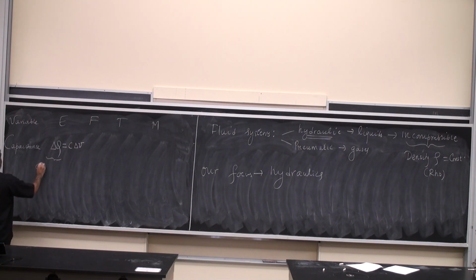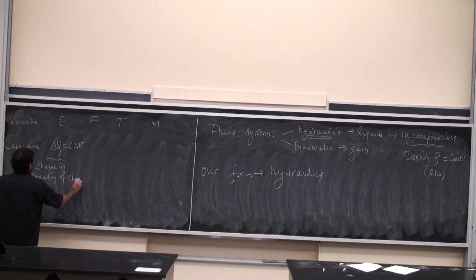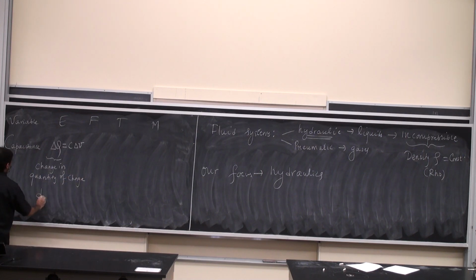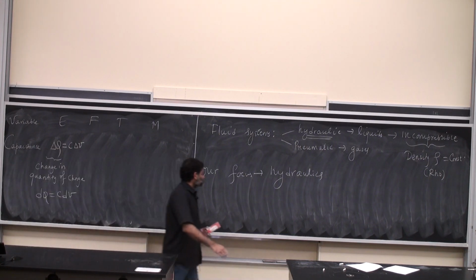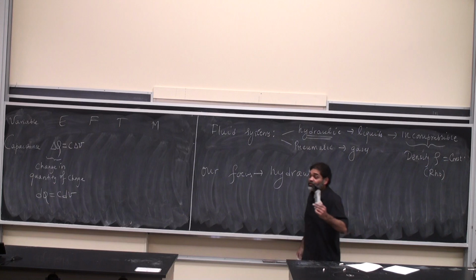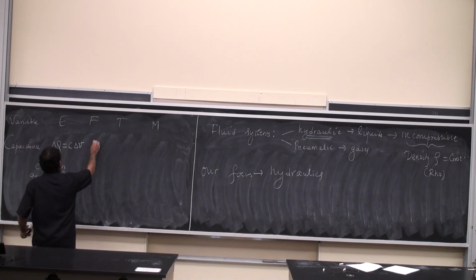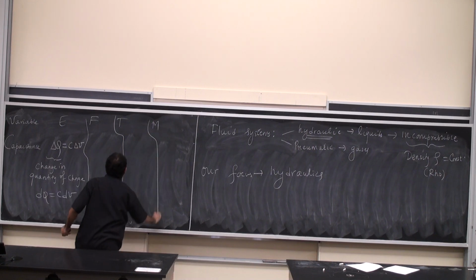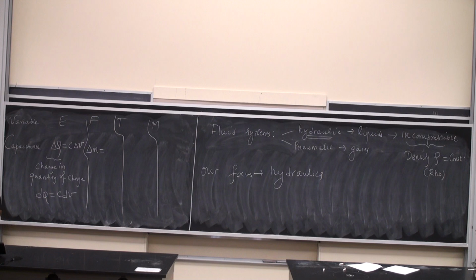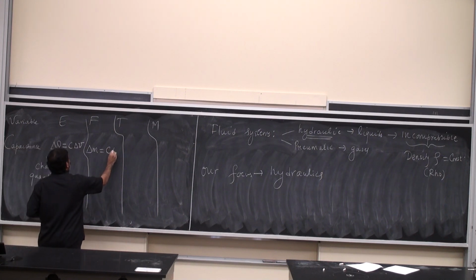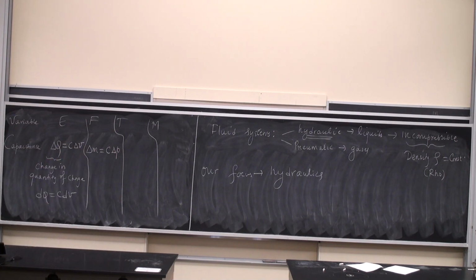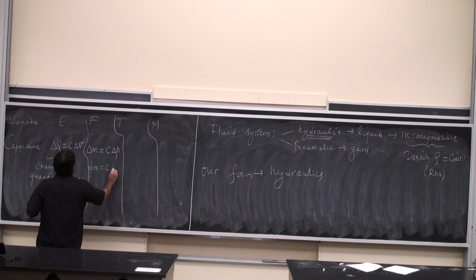This is change in the charge, in quantity of charge. Or you could also write it as dq equals c times dv if you want to write it in the differential form. Okay? Fluid systems. Quantity in a fluid system is the mass of the fluid. And change in the quantity is delta M. So I'm going to have delta M. Fluid capacitance, same symbol, unfortunately. And the voltage difference in electrical systems is analogous to pressure difference in fluid systems, or in a differential form. So that's C